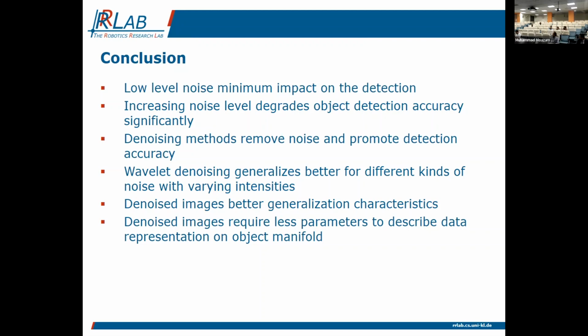How could we know which type of denoising filter to plan? Yeah, so by choosing a lot of different noise models, because the charts that I showed you have been taken across many noise modalities, right? So we have the Gaussian noise in there, salt and pepper noise, and all the others, and Brownian and whatever. And across all of those noise modalities, the wavelet one has proven to be the most versatile.